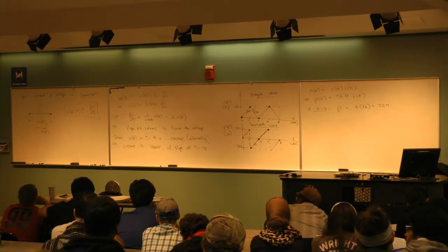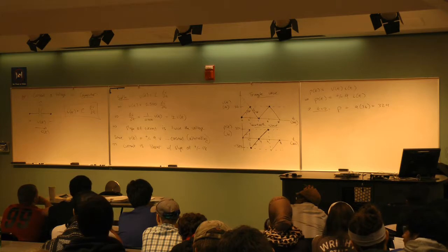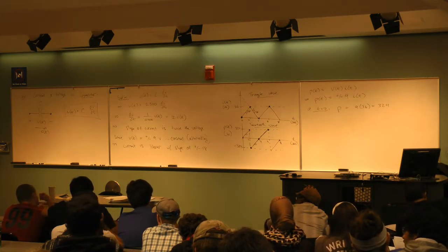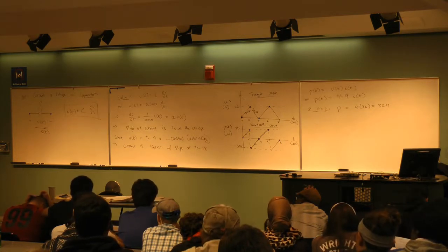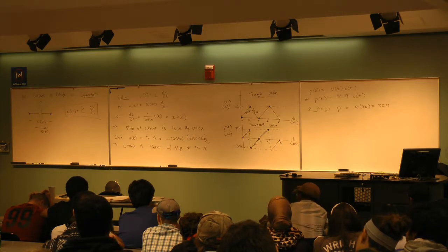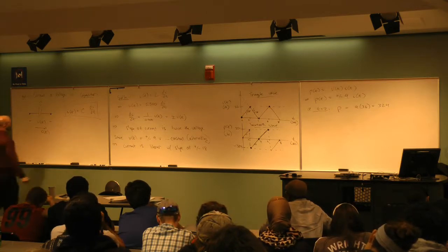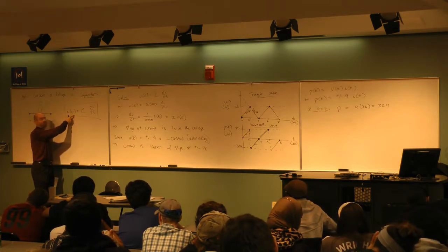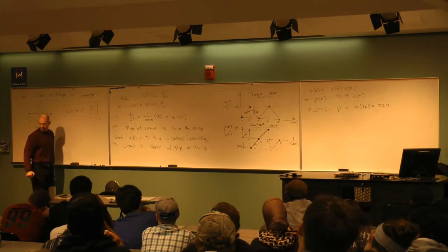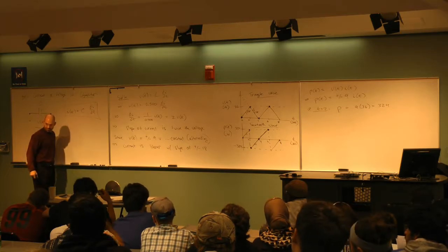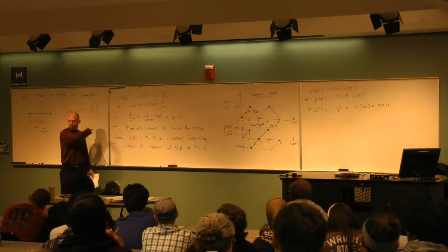So now, think about if I start building a circuit and I'm controlling one or the other, voltage or current. If I put in an inductor in there, right, V equals L di/dt, I can control the rate of change of the current by controlling the voltage source, or if I'm controlling the current myself, I'm changing the voltage with a rate of change of the current. If the same circuit has capacitors in it, then look what happens. I can control the value of the current that flows by purposely changing the voltage, or I can control the current source. And if I do that, that will control then the slope of the voltage. So this is the same kind of thing we just did here, except the interpretation's reversed.